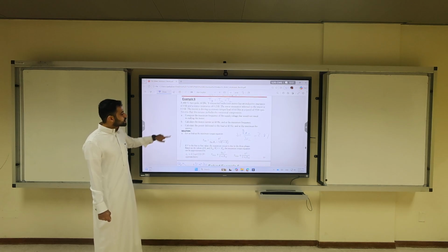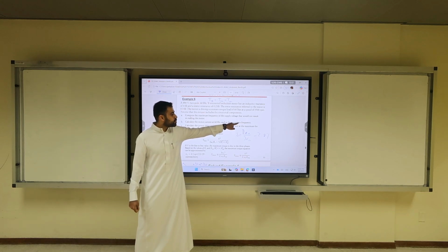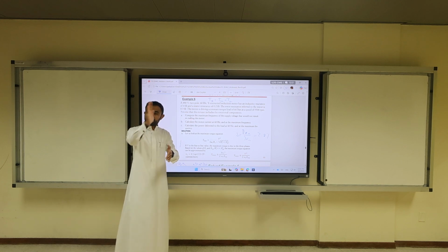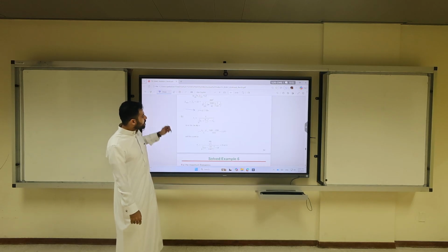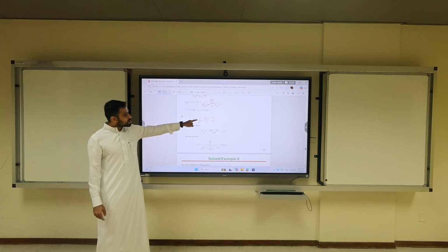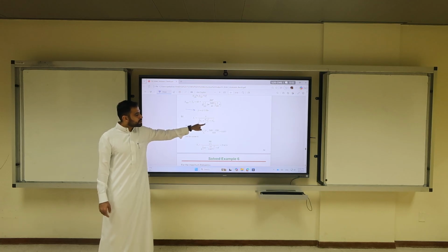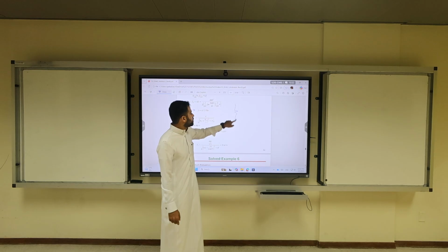Now, the other question is to calculate the motor current at 60 and at the maximum frequency, which is 67. This is easy. Go back to 360. Calculate starting current at 60 Hertz. Calculate starting current at 67 Hertz. So what are the equations? This is the equation for 60 Hertz. If you remember, this is the equation from 360: V over square root of R1 plus R2 prime over S, squared, plus X equivalent squared. He's using the equivalent circuit.